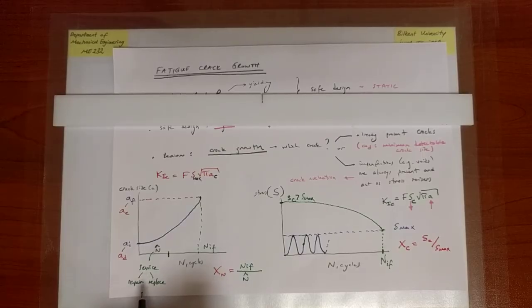That's why you take your car to the service, so that they do something about it. They probably have certain safety factors that are written in their service manuals, and they say that, okay, the so-and-so part, let's say the chain that connects your camshaft to the crankshaft, whatever, needs to change after so many kilometers or years, whatever, right? So that has to do with fatigue. They want to make sure that eventually you're sufficiently far away from failure to within a certain safety factor. Okay, so that is eventually a practical concern that comes out of all of that discussion.